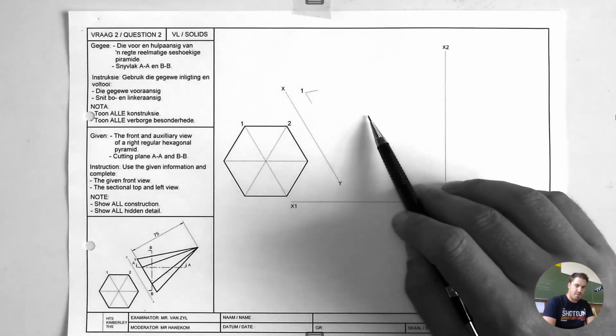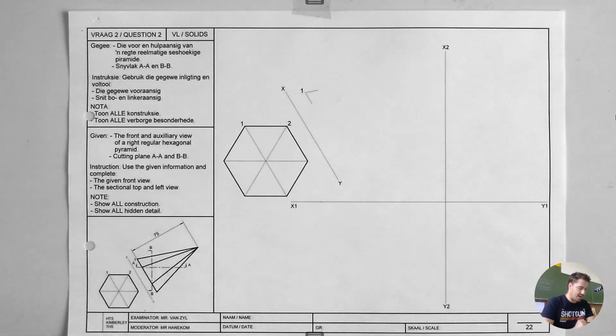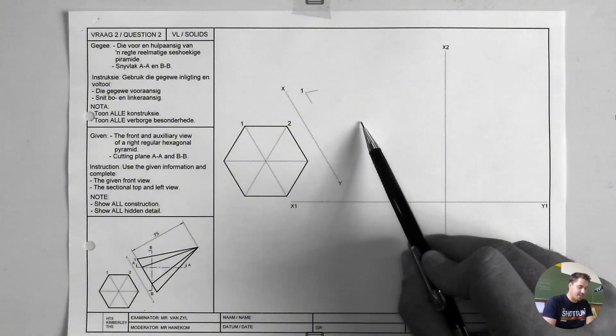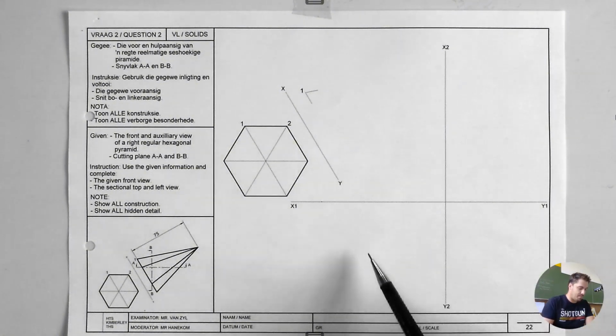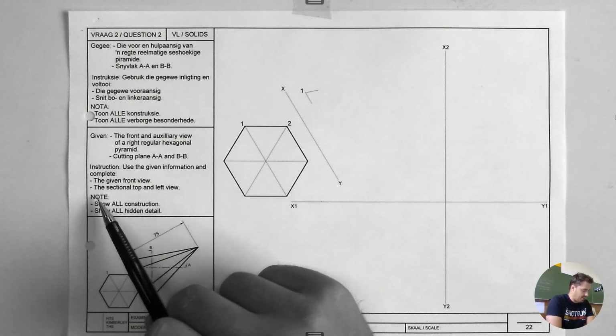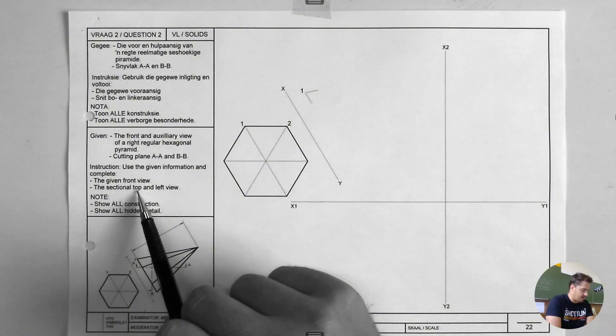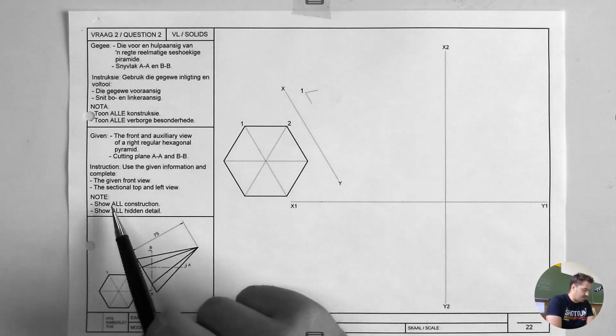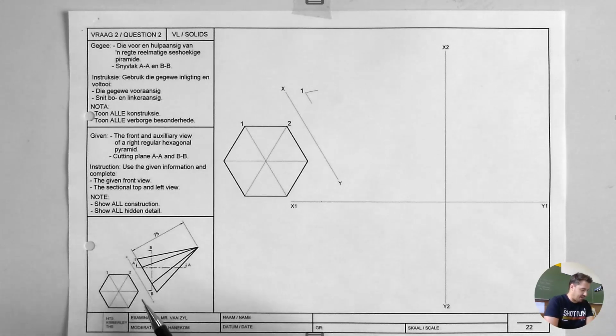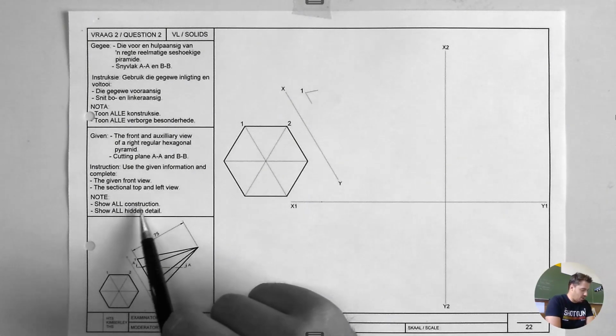So that means we have the front view here. It's first angle orthographic projection, which means to the right of it you will have your left view, and at the bottom you'll have your top view. All right, so the given front view and the sectional top and left view. So the left and the top view is going to be cut by the respective cutting planes. Note, show all constructions, show all